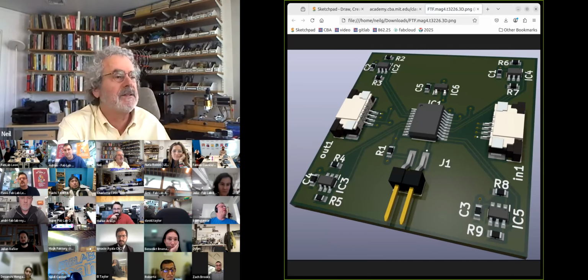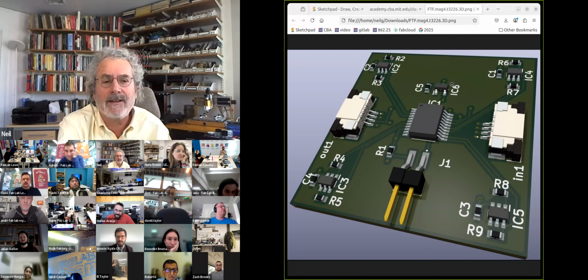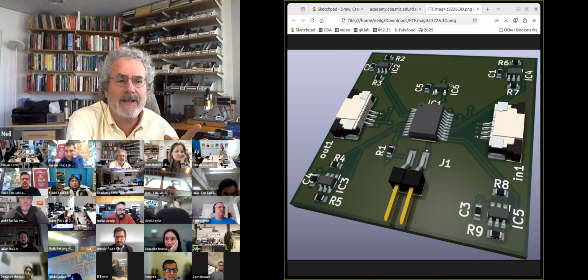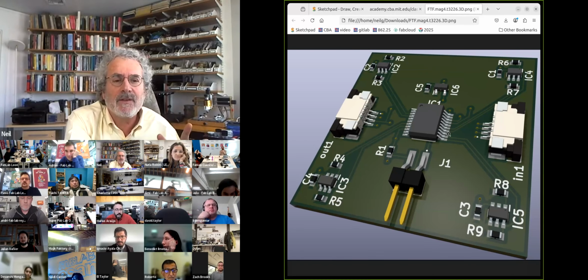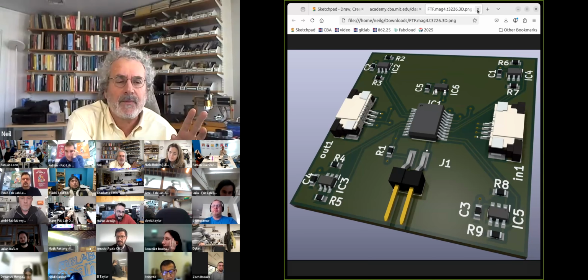So this is just this weekend, there was a circuit I was working on. I'll explain the tools. And so to make the circuit, I have to route the wires. The footprints are the pads I connect to. And then I also have 3D models of the parts that let me design around it.